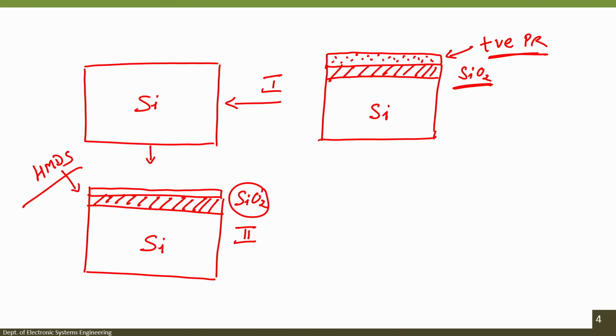So, silicon wafer, we clean the silicon wafer, then we perform the HF, then we rinse it and dry, then hot plate, then we can grow silicon dioxide. Of course, there are RCA1 and RCA2 cleaning. If you want to perform RCA1 RCA2 cleaning, if you have a new silicon wafer, you may not like to go for RCA1 RCA2.